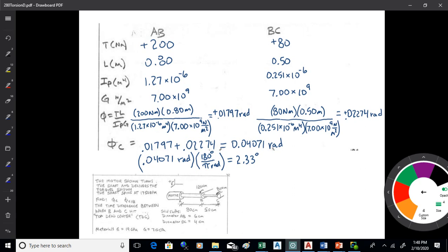The intake valve has to open at the right time. The valves have to close when the spark plug fires, right? Then when you got the exhaust, that exhaust valve has to open. That all has to be very, very precisely timed. If that isn't working right, you got problems. And that's all based on the crankshaft, right? You got lifters and all sorts of things coming off the crankshaft. The crankshaft spins and makes all that happen.